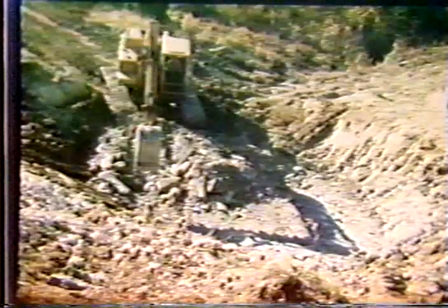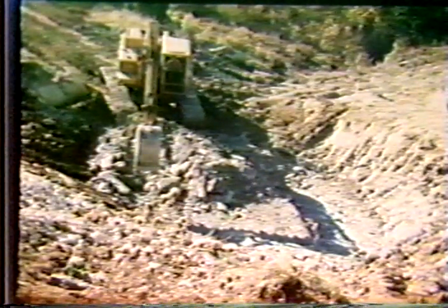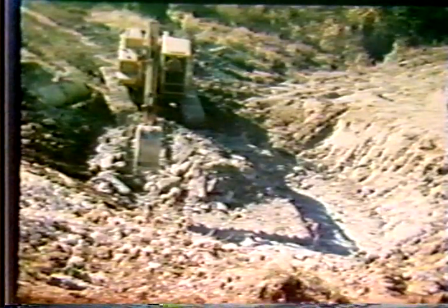So what the engineers did there, they came back in and they already had the berm stone in place, which didn't work, so they just simply stockpiled it very close to where the failure was. So they removed the material, they went down and started building the shear trench. Used a backhoe to excavate it down several feet. Just another view of the back slopes that we talked about that you can build on 1 to 1, 1.5 to 1 slopes.